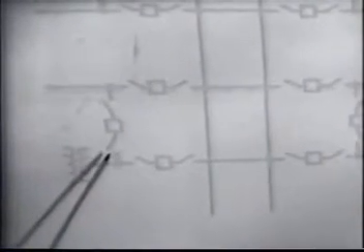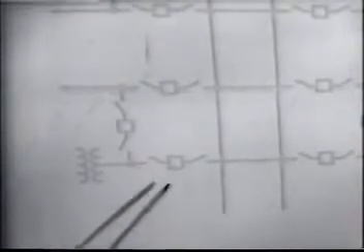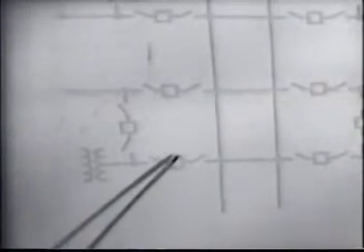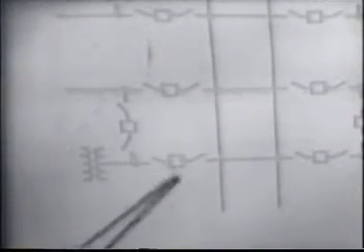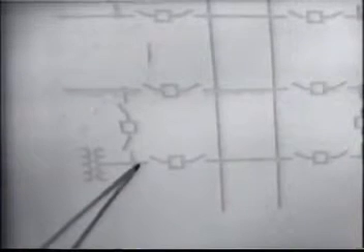So you have the flexibility of being able to maintain any of the breakers without interrupting service, and you have, of course, then added the complexity of having to relay or control these two breakers simultaneously to interrupt a fault in the transformer, for example.